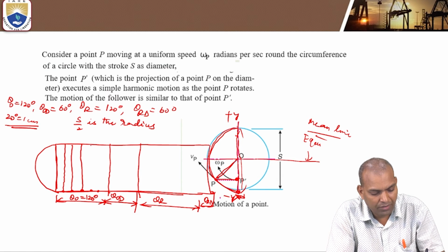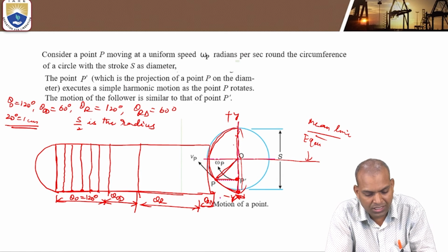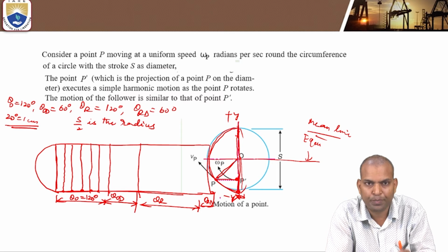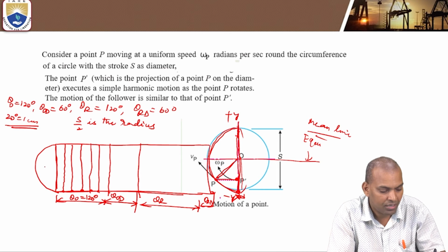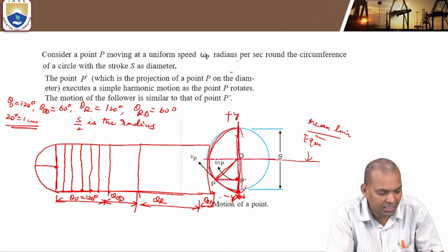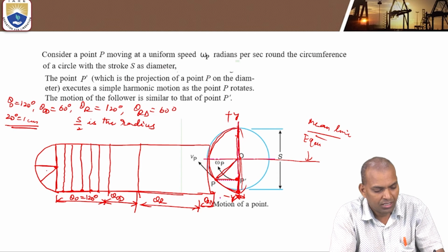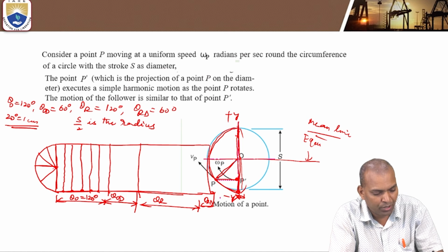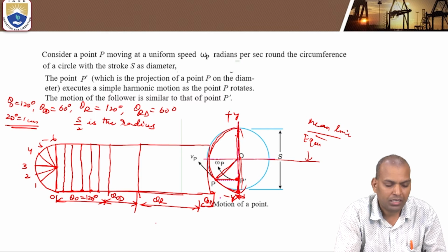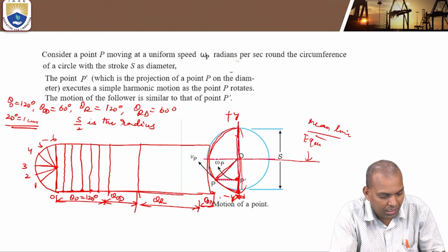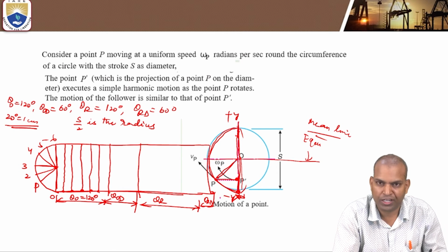Now, after drawing these vertical lines, this is the vertical line from minus y to plus y. Now this is the semicircle. The point P has angular motion, so divide it into an even number of equal parts, that is 0, 1, 2, 3, 4, 5, 6. Now I am considering this point P on the path of projection.